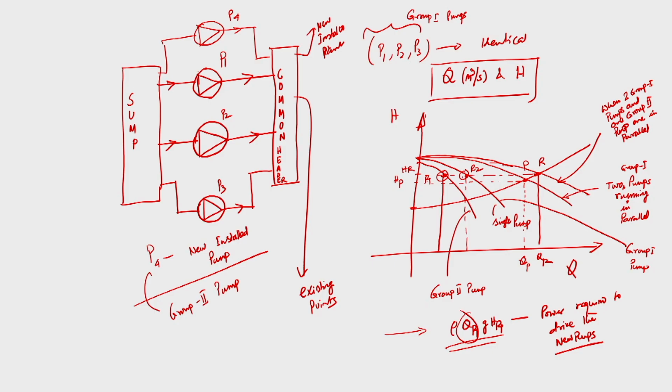So, I do not know if the existing system resistance becomes minimum. This will happen, and for that pump 2 may trip if the power requirement goes beyond the power supplied by the electric motor. In that case, what do you have to do? This is a very big problem. So now I will briefly discuss how we can eliminate this kind of problem.